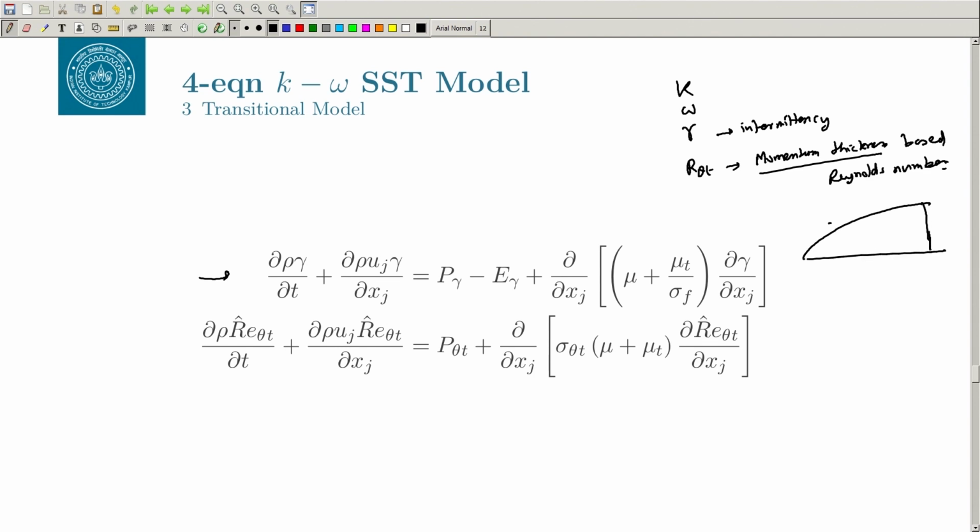One is of course your boundary layer thickness with delta, where you say that your u is equal to 0.99 or 0.9 or 0.95 of u infinity, or you can have something called theta, which is given here, momentum thickness, or you can have a delta star, which is basically the displacement thickness. Without going into the details, this is a fluid mechanics thing, and I expect that you go and read it.